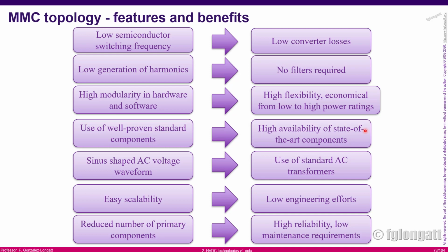Well, there are several advantages, and one of them is a massive reduction in the switching frequency, okay? And why is that extremely important? Because if you reduce the switching frequency, you are reducing the losses created by the commutation process. That is one big positive point, okay?